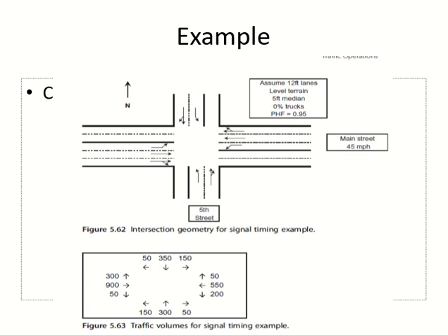Now for the left turning groups, it is very easy because it's only one movement, so you just put the left turning movement with the group. For the straight we have 2 lanes in each direction. You can go from here or here, so we have to divide the flow. We don't have equal distribution, especially because this one is also for the right turning. So this lane group will have 55% of the straight, and this one will have 45% of the straight plus the right.